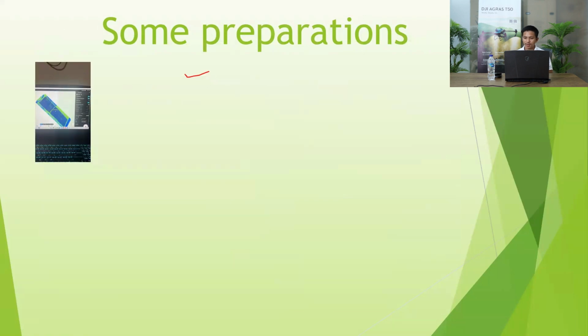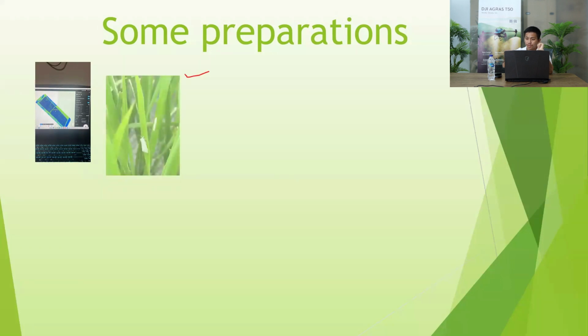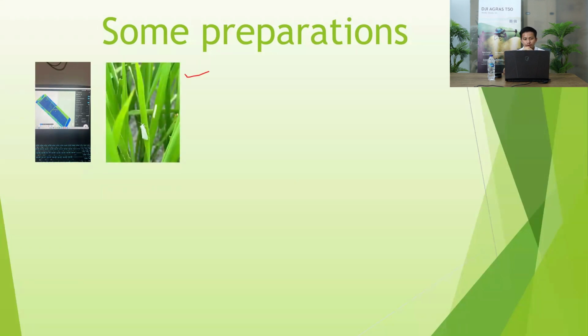First, what I did is I checked in Terra and generated my plan in DJI Terra, and I checked everything. If you have Terra, you can check even 3D flight paths, okay, how the drone will behave. If you see some points going very low and it's not safe, you can simply move that. You can do it in Terra, okay. And you can check the farm, because sometimes the farmer gives you the wrong chemical, then you need to correct it to the right chemicals. So which parts are exactly being sprayed. So this is in the site.